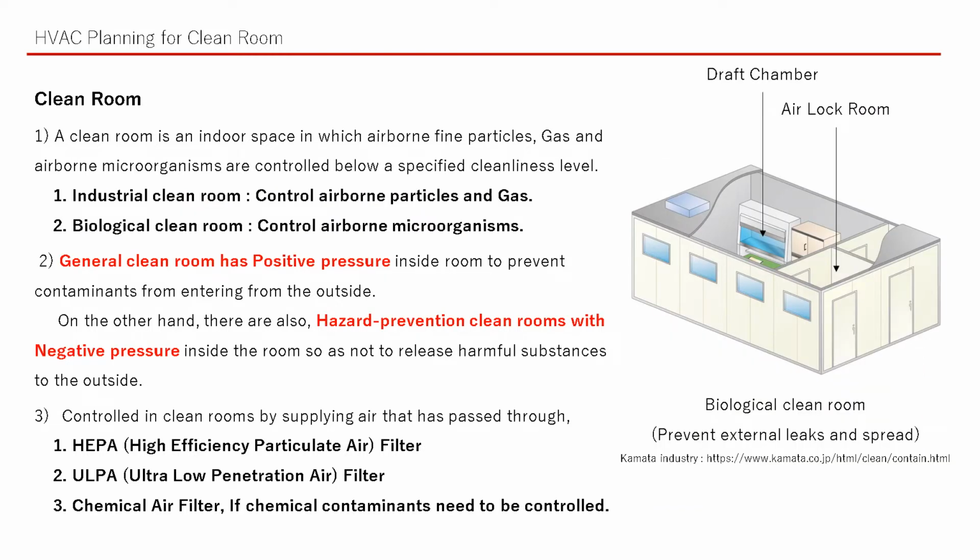Item 2. A general clean room has positive pressure inside the room to prevent contaminants from entering from the outside. On the other hand, there are also hazard prevention clean rooms with negative pressure inside the room so as not to release harmful substances to the outside. The preconceived notion that clean rooms are always positive pressure can lead to major failures and dangers.